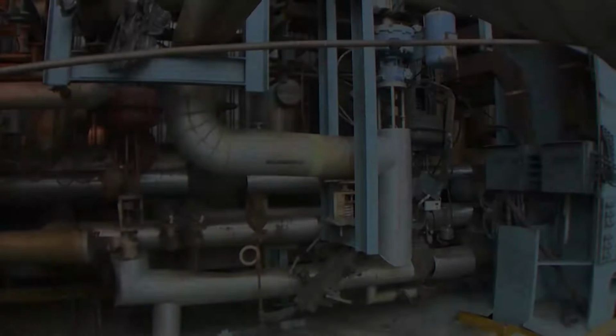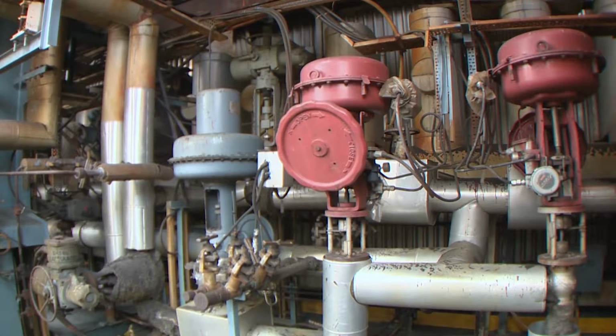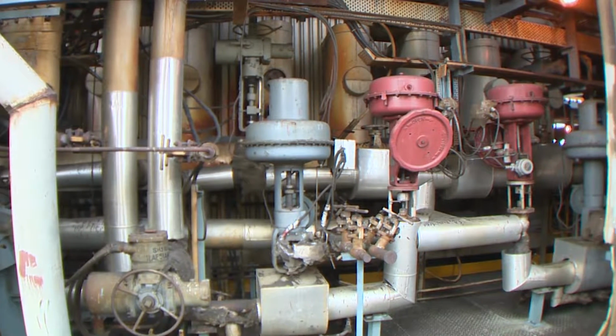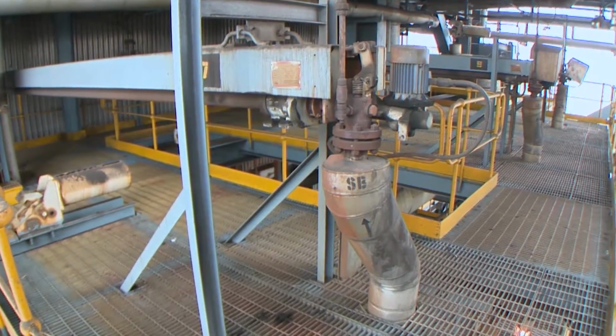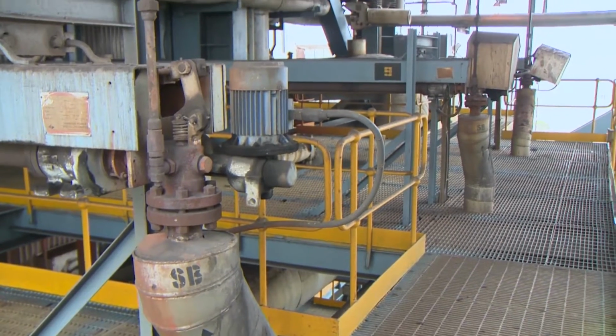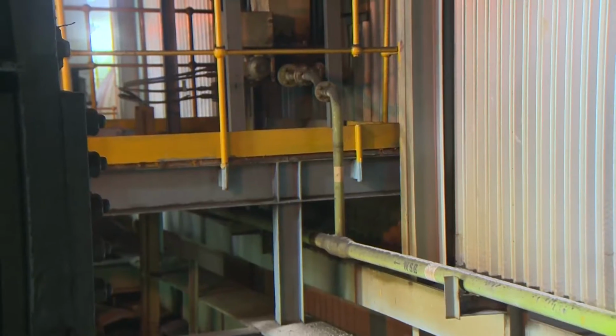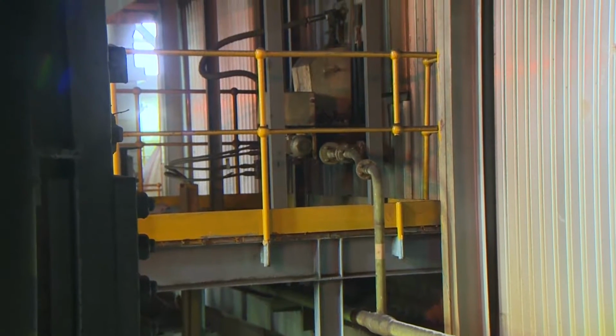Steam temperature control. Desuperheating spray system has been provided for maintaining required steam temperature. Cleaning devices. The superheater, reheater and economizer coils are cleaned by long retractable steam soot blowers periodically. The furnace is cleaned by online water jet lancer periodically.